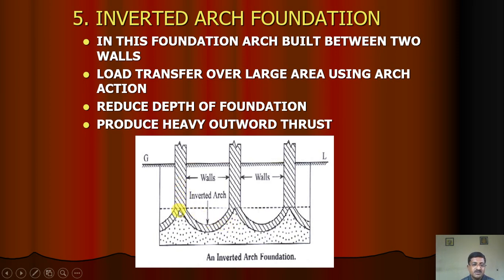So you can see, as in normal arch action, it is the same thing, but an inverted arch. This column is giving pressure on these arches, right? And because of the arch action, it can sustain the load. More skill is also required to construct this, but nowadays it is not used in practice.